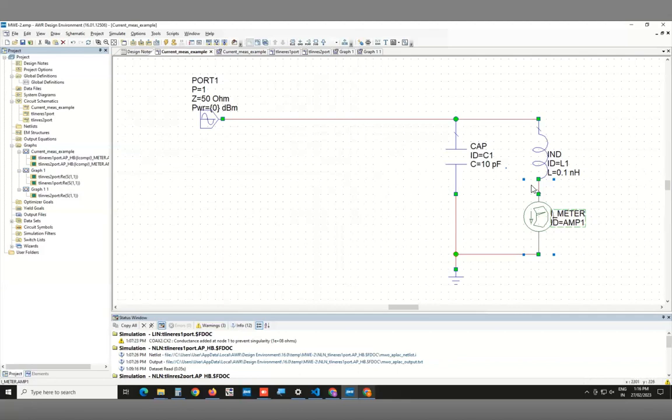The only option you have is to change the ratio of L's and C's, right? Because Q is proportional to capacitance, R is fixed, and omega resonance is fixed, because you want some resonator at a fixed frequency. So what it means is that you have to make the capacitor as large as possible and the inductor as small as possible. Now that again is not practical, as we discussed, because you can't make arbitrarily large inductors and capacitors at microwave frequencies. So the only way you have is to somehow control how much dissipation, and you do that by breaking this direct coupling to the 50 ohm environment and putting in a coupling capacitor here.